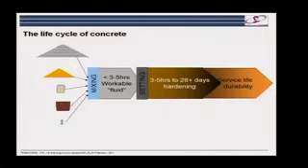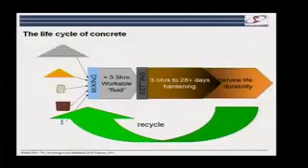28 days is a pretty arbitrary figure. It's just 4 weeks, so it makes it easy in terms of testing. But at 28 days, you will have about 80% of the ultimate strength of a concrete. And then over the next decades, or even centuries in some cases, you will have the service life and the durability. At the end of the life, as I said, you can actually break the concrete up. You can come back to these aggregates here. You can even put the other material back into the cement kiln, and you can recycle everything, depending on the economics and the logistics of the process.